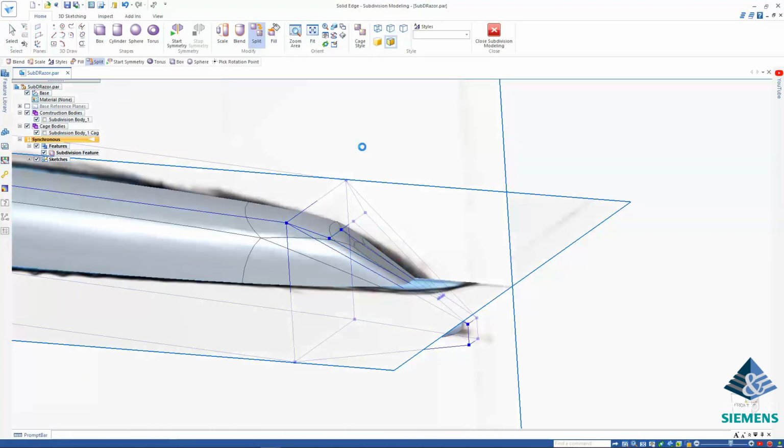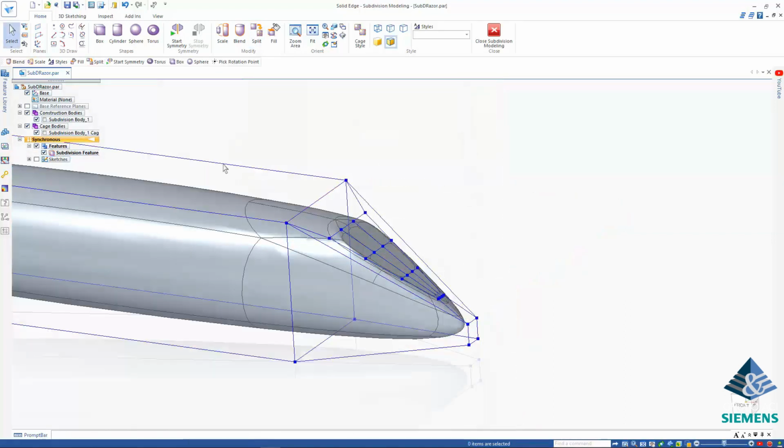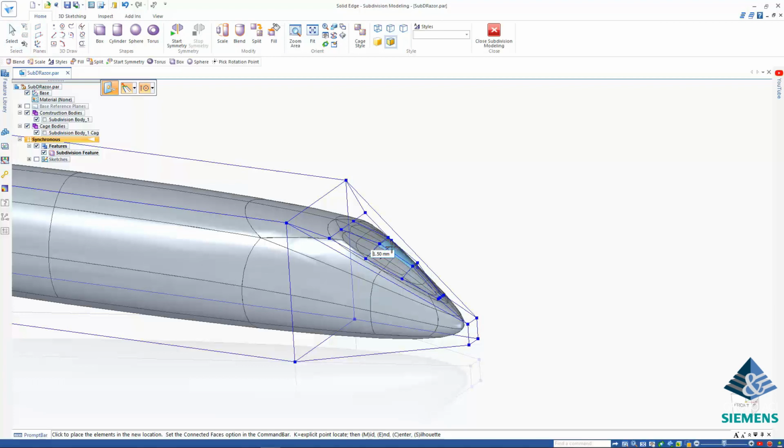Now, by splitting the newly created face into 9 smaller faces, we have greater control over how the finished model will look. Using the tip option when making a move forces the connected faces to extend, trim, or change orientation, resulting in the bump shape that we desire here.